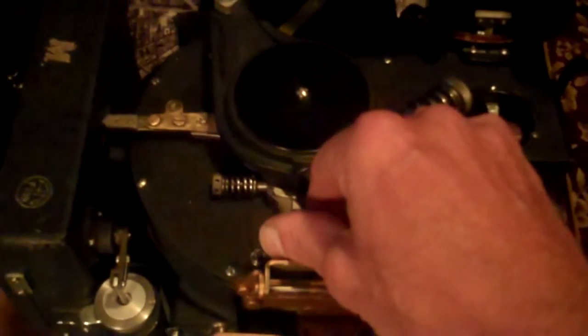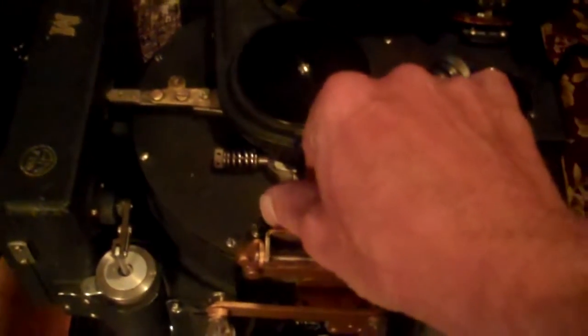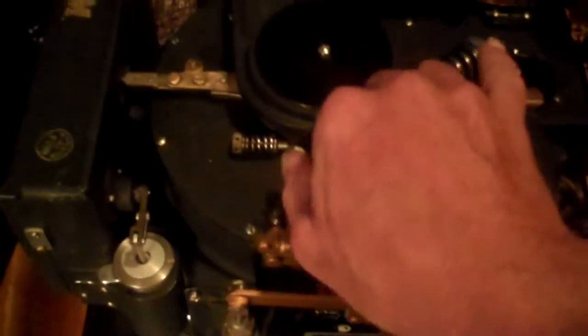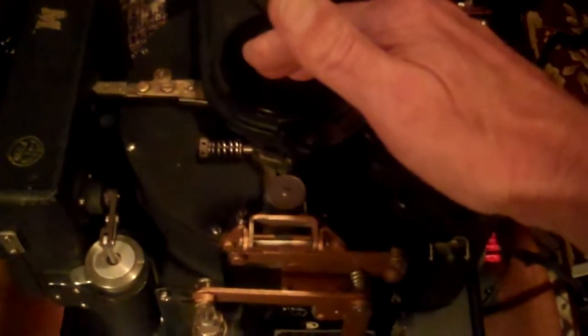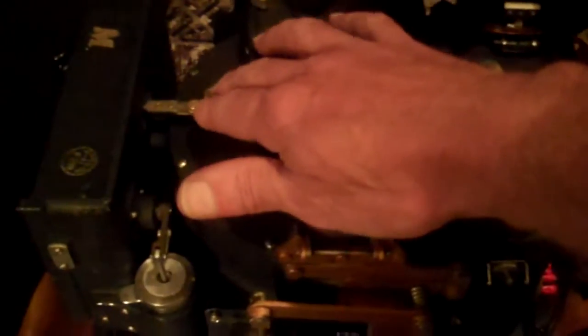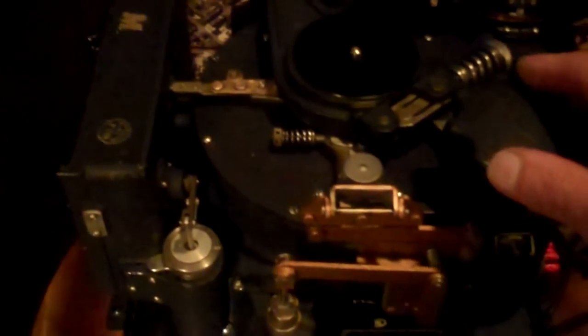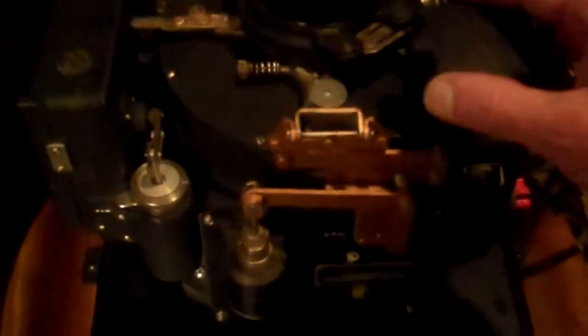During the early phases of the bomb run, the autopilot clutch is engaged. At this point, the stabilizer gyro is stabilizing the autopilot. As the sight head is adjusted left and right to keep on the target, it communicates this information with the pilot's directional indicator, telling the pilot which direction to turn, or feeding this information through the linkage to the autopilot. The bombardier can also fly the aircraft using the bombardier's turn knob.